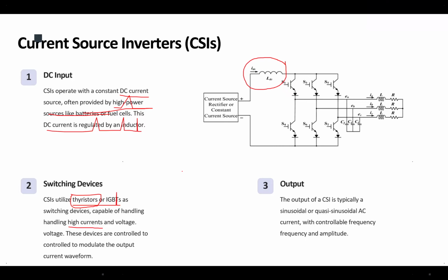Okay, so you need a redundant circuit in order to control the turn on and off of the thyristors. This is the main difference between the thyristors and IGBT. So by that being said, you might guess what the basic challenges are when you want to have current source inverters. And we already talked about the general challenges of the voltage source inverters in previous sessions.